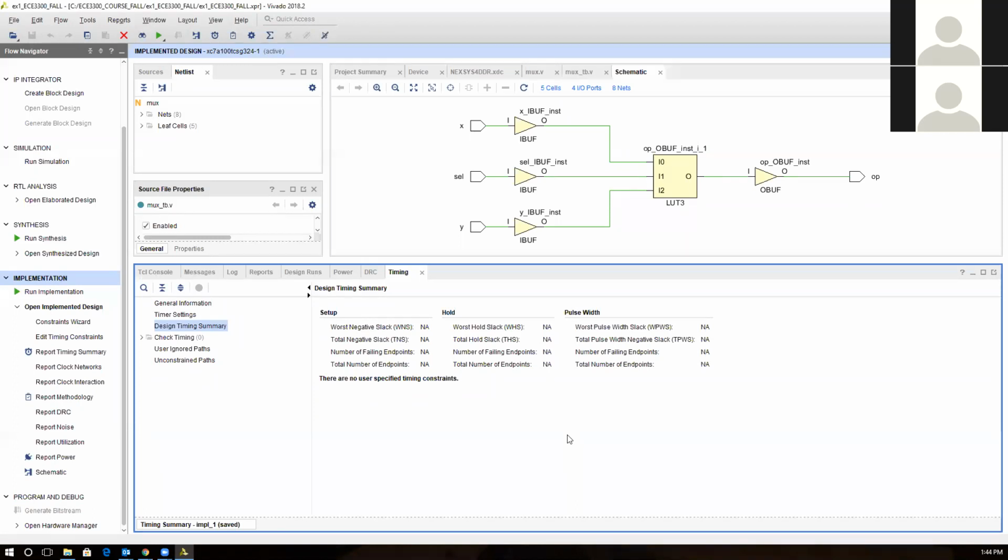It's running the bitstream. You know what bitstream means? It's taking the code and generating on and off switches, binary numbers. So it will map on the chip and turn on the right lookup tables and hook it up with the three switches and the one LED we're going to have on the board. And momentarily we're going to start demonstrating that.